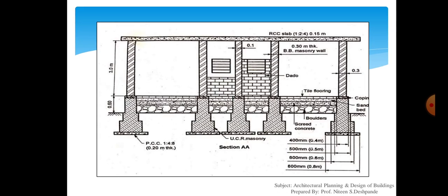You can see from the bottom there is a wall cut, then some space, then the part of the WC. Because we are seeing on the right side, there is a ventilator shown over here, then dado up to a height of 1 meter, then a toilet, a bathroom is shown, the ventilator we can see over there, dado, and another room.